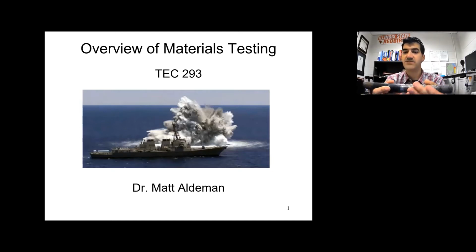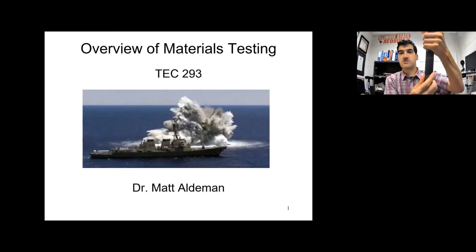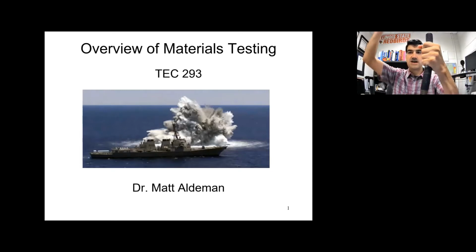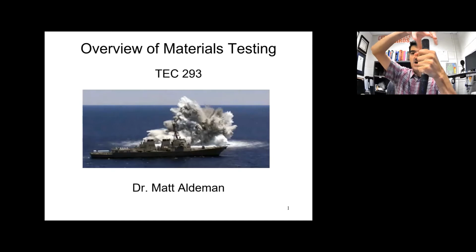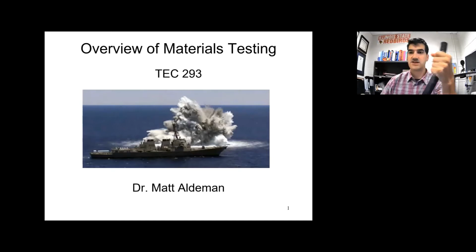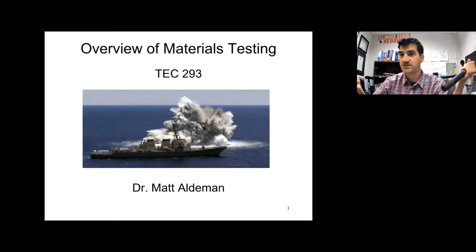So this side of this screws into a threaded hole in the hub, and then the blade gets set on top of this, and then a big nut goes down on top of this, and then it gets torqued to a really high value. I don't remember the torque spec on this, I have it somewhere, but it's a very high torque spec.